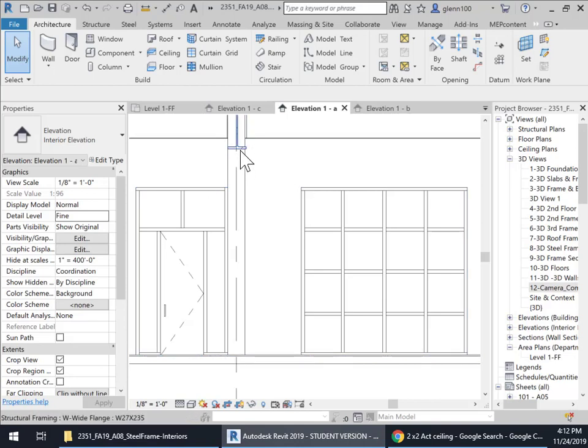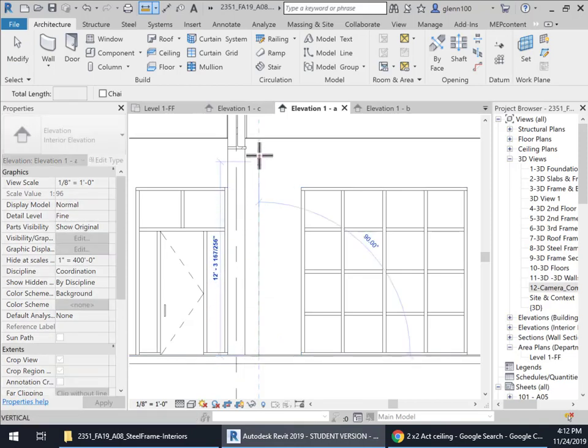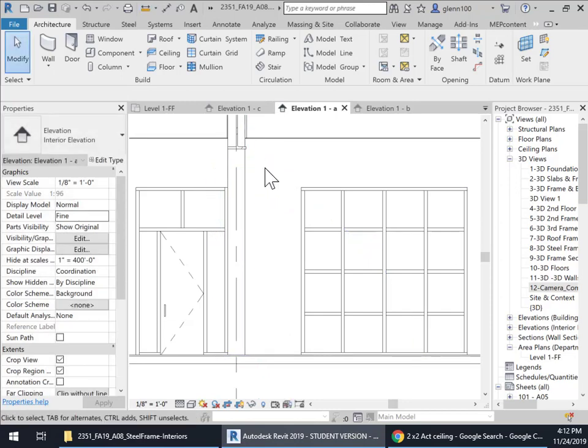And we've got enough room underneath this girder. Probably, let's take another look here. Okay. The girder is right at 13 foot 2 inches. So if we go up to 12 feet, we'll have a foot underneath that. That will probably be enough. If it's not, we can always come and lower the ceiling or whatever. But I'd like to get the ceiling as tall as I can. So we're going to assume 12 feet for our ceiling. And then let's go back to our finished floor.